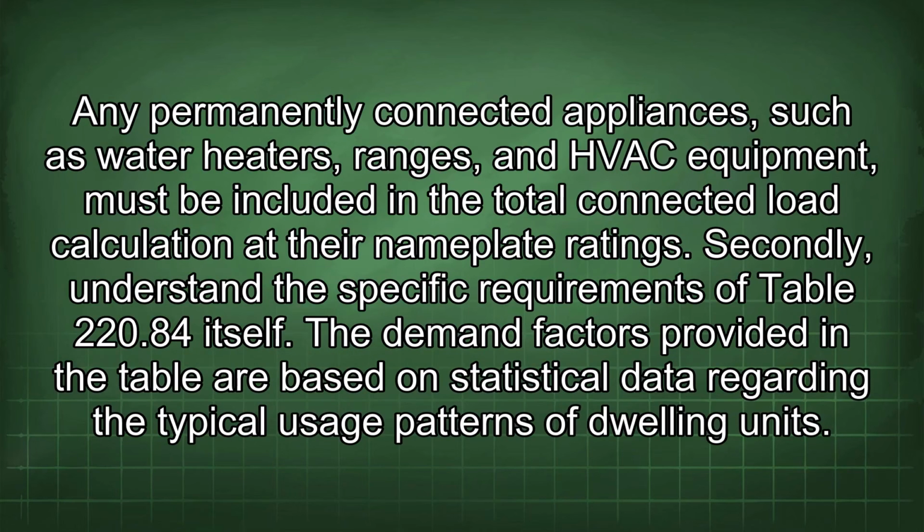Any permanently connected appliances, such as water heaters, ranges, and HVAC equipment, must be included in the total connected load calculation at their nameplate ratings. Secondly, understand the specific requirements of Table 220.84 itself.